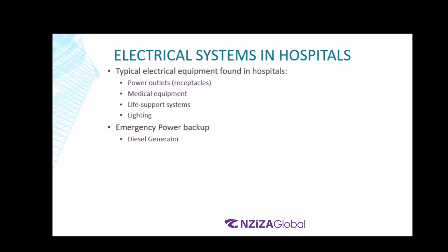It might be fine if we are doing that over here in the conference hall, but of course, if it is in an operating room, it is not possible for that kind of scenario to sustain. For that, we require the uninterrupted power supply, UPS. In addition to the DG set, the first line of defense for operating rooms when there is a power outage is UPS. Then after 10 seconds, whenever the generator kicks on, that is fine. But for that 10 seconds, we need to have a proper UPS design for the emergency power backup. All right, with me till now?